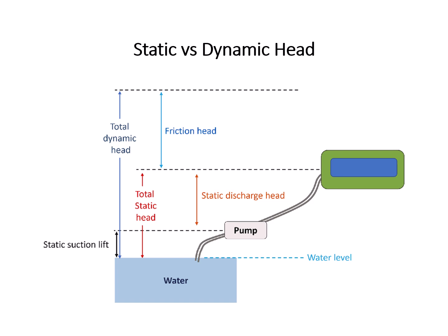Static discharge head is from the center line of the pump all the way to the discharge point, which is here. So this is the static discharge head, and this is the static suction head. The total static head is the summation of the static suction head and the static discharge head.